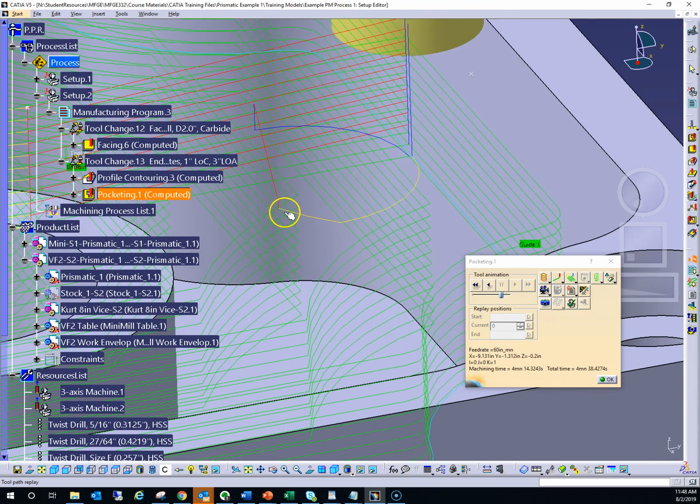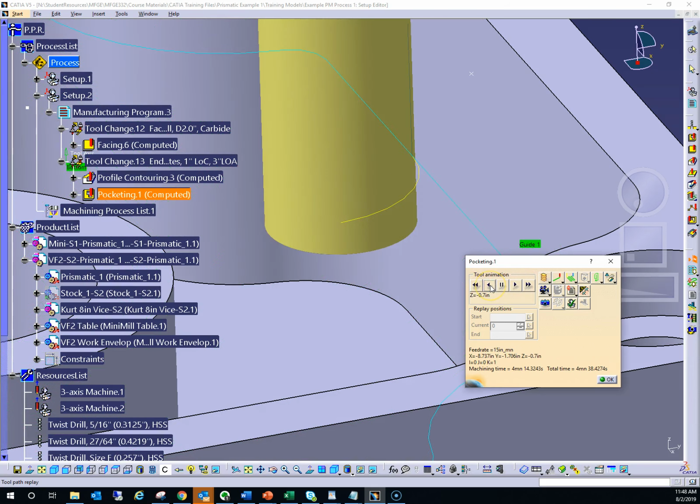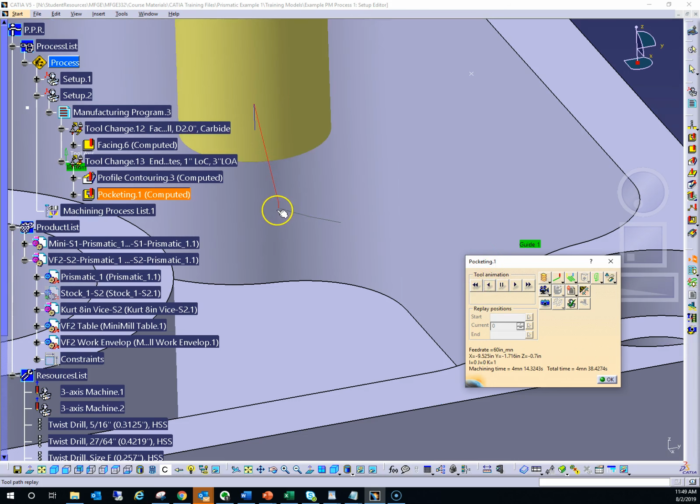We can see here already, this is the helical move on the approach. Actually, let's rewind this. Let's go forward and back up. So this is going forward, takes us all the way to the end, and then backing up gets back to the last motion, which is the finishing operation, the light blue toolpath. This is the circular lead-in that I added. The tool is going to come in on this circle and then engage along the blue toolpath for the finishing pass. If I back up one more step, I should see the helix here.